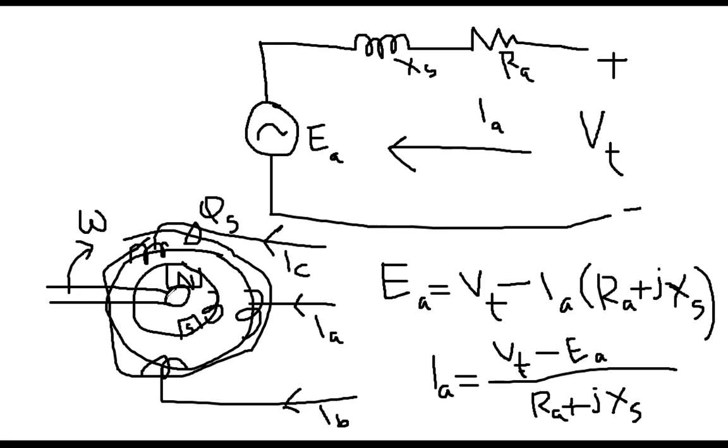When the shaft is rotating and a physical north pole and south pole are placed on the rotor body, but these coils are static, then when the motor is running, there will be a voltage built up on these coils. For phase A, this is the internal developed voltage. But it will try to oppose the main voltage. For example, here you applied the voltage VA, here it is VB, and here it is VC. This internally generated voltage will start opposing the main applied voltage. That's why you are seeing the minus sign here.